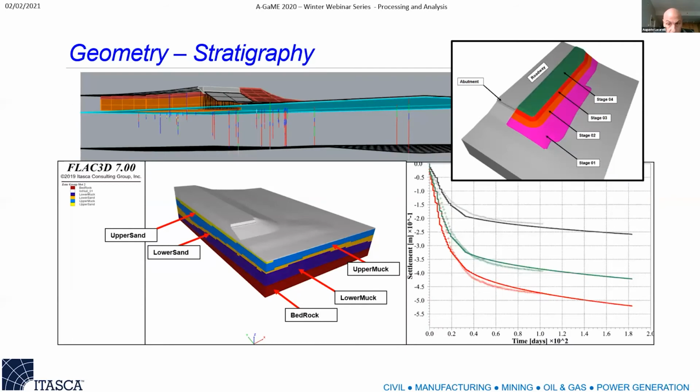Let's move forward to another project. This is again a 3D representation of the 35W bridge extension. This is the new embankment that was built, and the soil was improved, quote unquote, using wick drains to accelerate the consolidation process. Here on the lower right, it shows the measurement and the back analysis just using the CPT data.